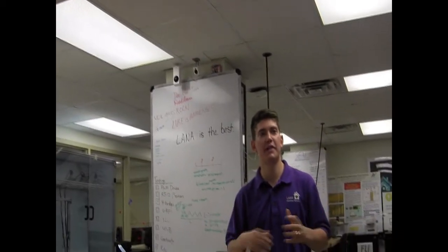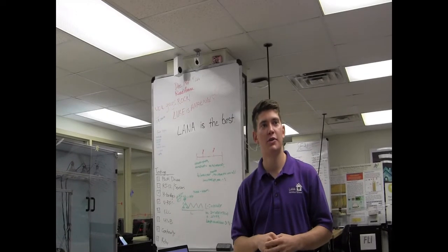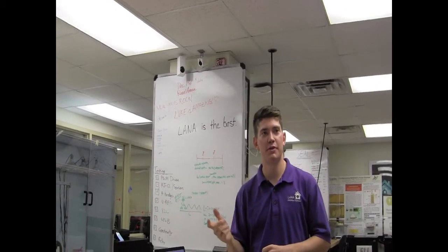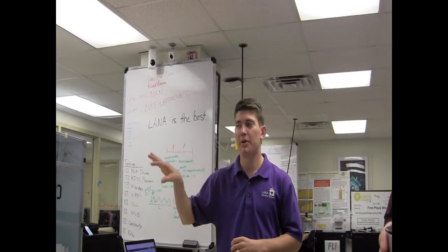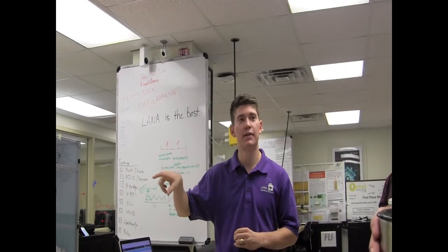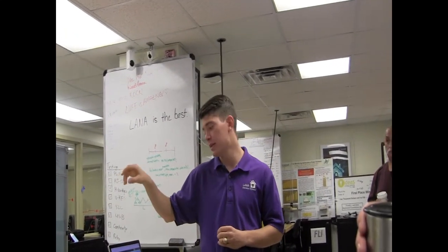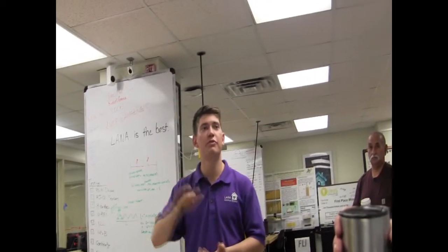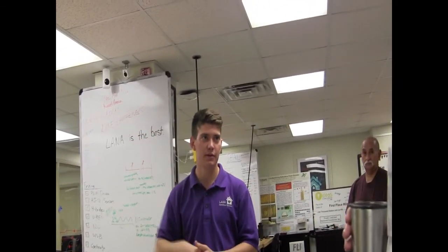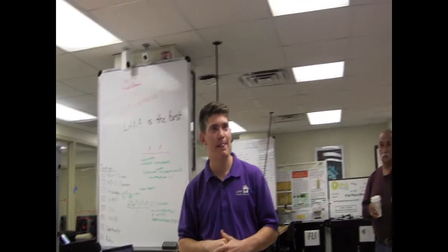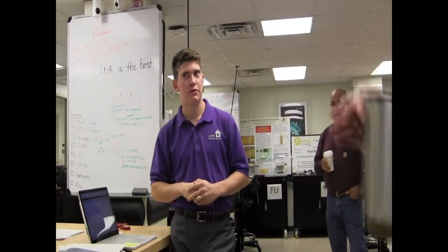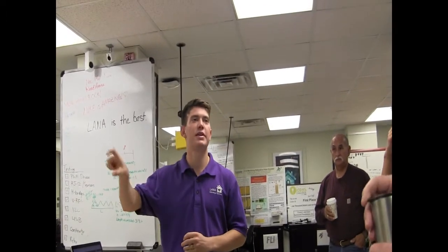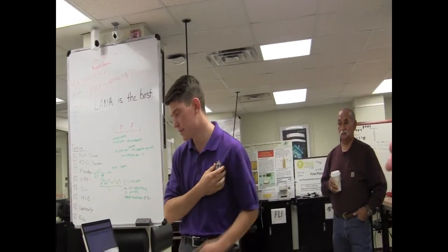So relative humidity is measured in percentage. Whereas you would say plus or minus 2 degrees for temperature, from 45 would be up to 47. Plus or minus 5% relative humidity from 45 would be 40 to 50%. You're mixing your units. Plus or minus 5% of humidity, not of the measurement. Correct, because relative humidity is measured in percent. Got it.